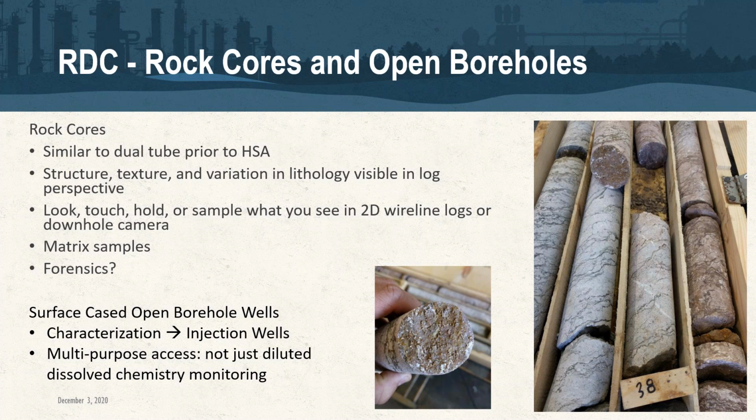the methodology or the type of construction that we would like to have for the wells within the consolidated geology is to have surface cased open borehole wells. And the benefit of these is that you can use them for an extended number of characterization tools, but then ultimately they can be used for the remediation of the geology itself and the groundwater by use, for our purposes, for injection wells. And so these are multi-purpose access features. They're not just drilled into the geology for the purpose of looking at diluted, dissolved chemistry for monitoring purposes only.